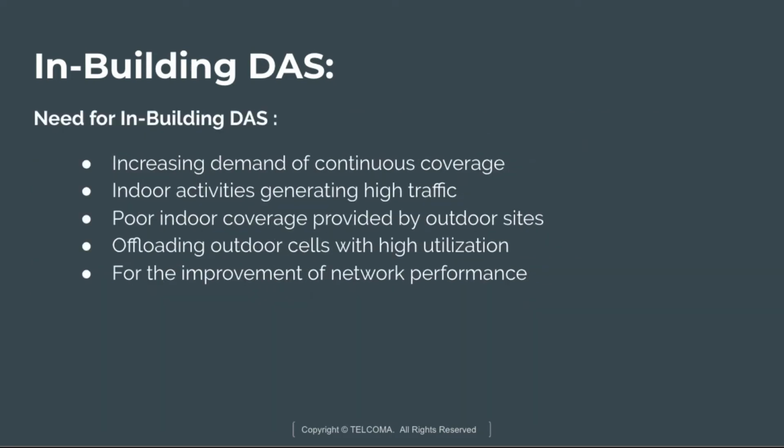The need for in-building DAS arises because of the increasing demand for continuous coverage, because of indoor activities that generate high traffic, due to the poor indoor coverage provided by the outdoor sites, and due to the offloading of the outdoor cells with high utilization. For the improvement of network performance, there is a need for providing an in-building distributed antenna system.